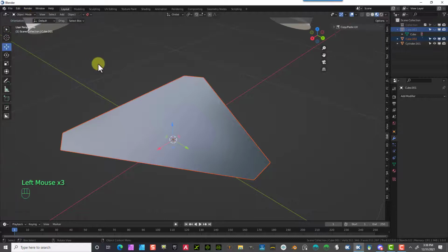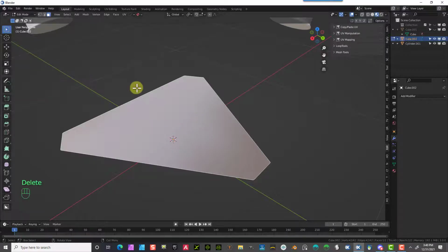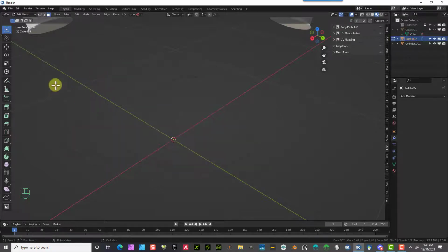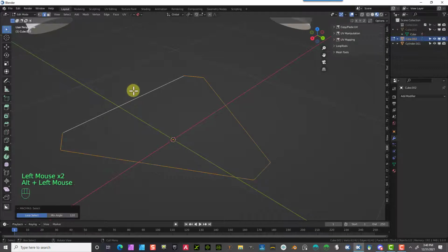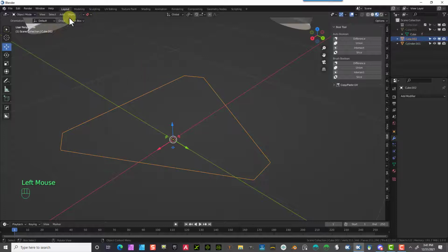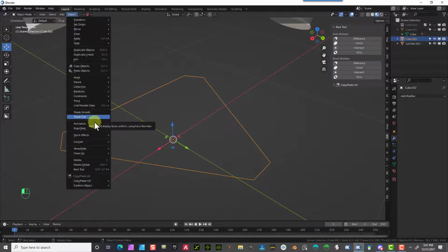So hit the polygon, go to edit mode. Okay, hit the delete key. Only faces. Okay, so now you just have the edge. Now Alt key, select it. So now I've got to go to object mode and use the convert tool to curve.